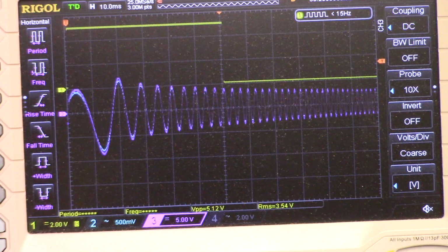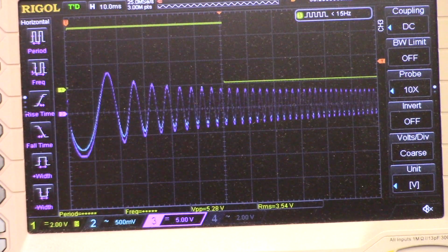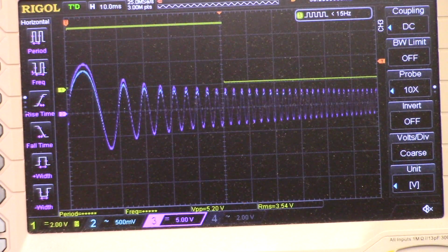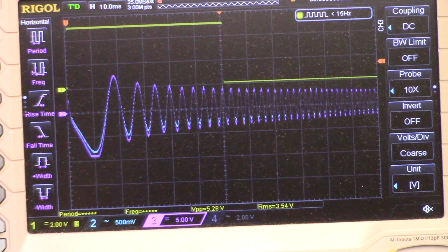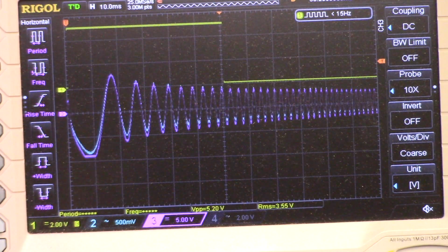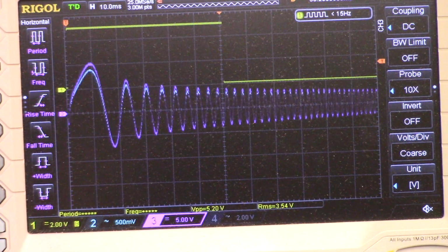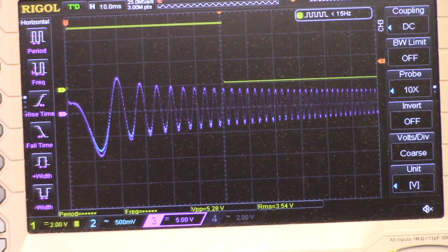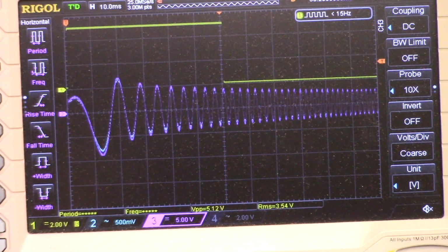Of course, you can pick your own favorite op-amp circuit, inverting versus non-inverting, and your own favorite op-amp for that matter, to make your own active filters and derive the gain expression in ways very similar to what we did above. There are a few things you have to watch out for if you want to apply these ideas at radio frequencies. For example, op-amps have a bandwidth parameter known as the bandwidth gain product, which limits the maximum frequency and gain you can employ for a given op-amp. I'll link in some information below. We might revisit this in a future project and video.